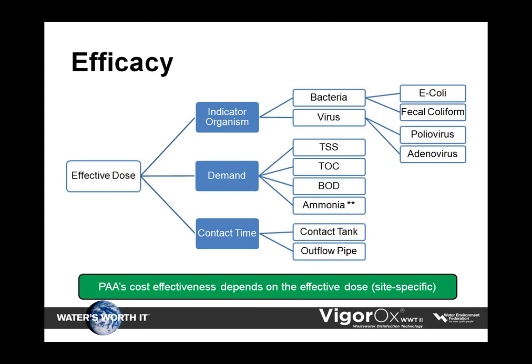Finally, the contact time available has an impact on the required dose. In general, higher doses are required to achieve disinfection in shorter contact times. So let's review these three factors in more detail.